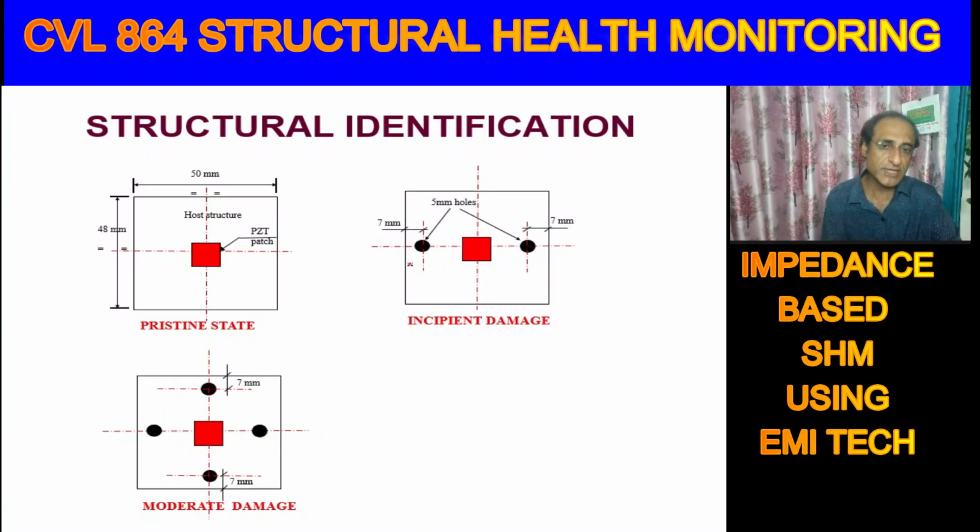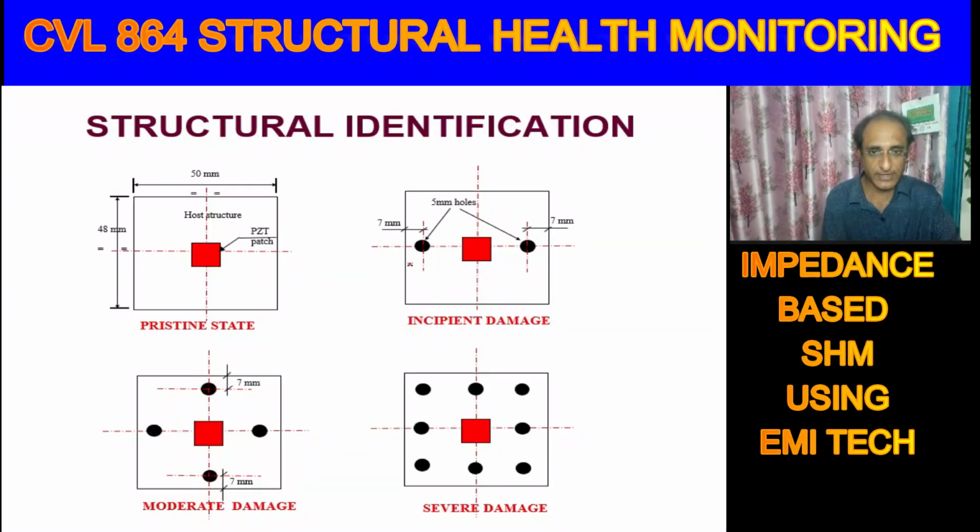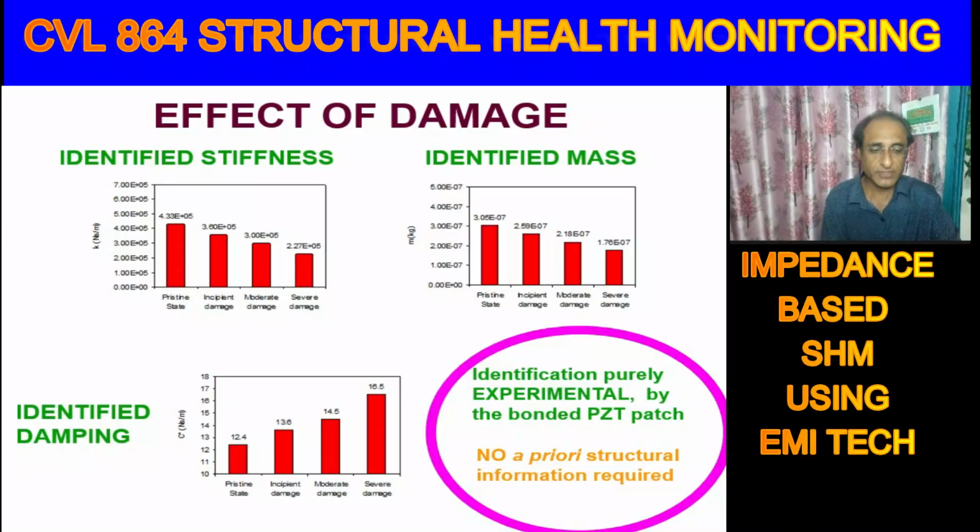Now, what is the advantage in damage detection? We can make use of this fact to find out how the stiffness terms and the damping terms are changing with damage. For example, here for this structure, as the damage is happening, the stiffness is reducing and the damping is increasing, because that's what happens when we have damage. In general, the stiffness reduces and the damping increases. But this kind of identification gives us a more parametric analysis, because earlier we were just doing visual inspection of the signatures without going into the structure part. Now here we are going deeply into the structure part.